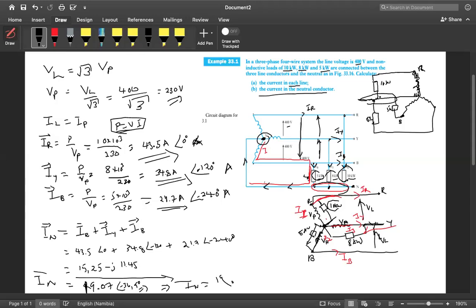Now you will see that you have a loop here, where in that loop you have your phase voltage, then your resistor and the power being consumed there, and your line current, which is also equal to your phase current. So it's like you have three simple circuits. We've gone to that arrangement where this is our phase voltage, and this is our line current, which is also our phase current.